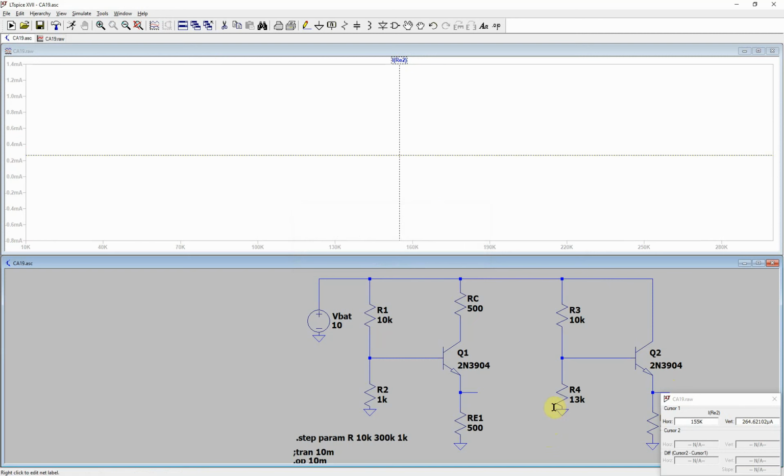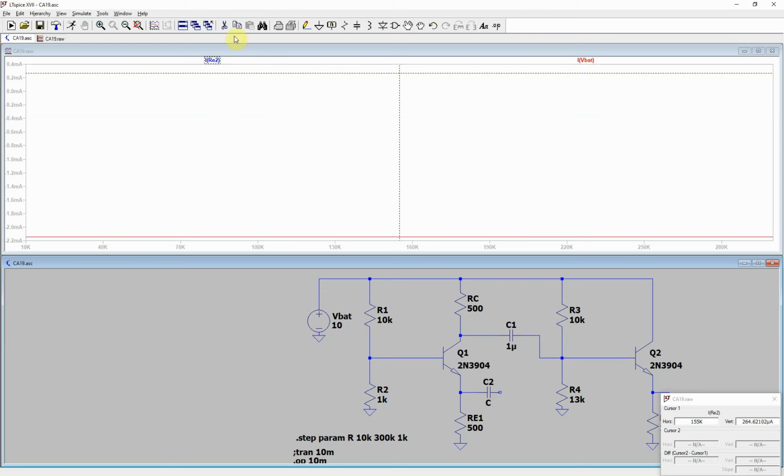So now we're going to take these two together and we are going to connect this output to this input. So the impedance seen by this capacitor is going to be 500 in this direction plus something really big in that direction. So let's just say 10 kilo ohms. So this doesn't need to be too big, so we'll just put in a micro there. We're going to capacitively couple this one for our output. We're going to put in our input source here.